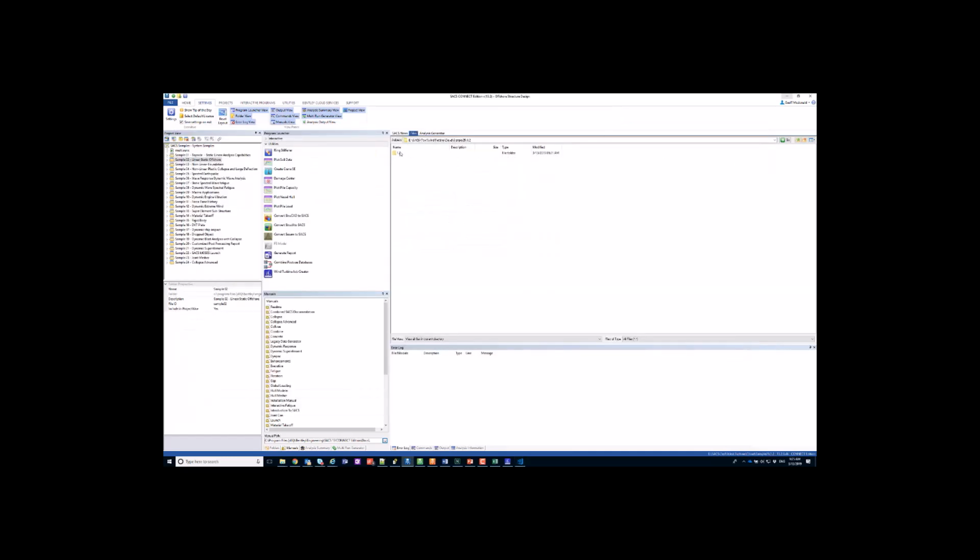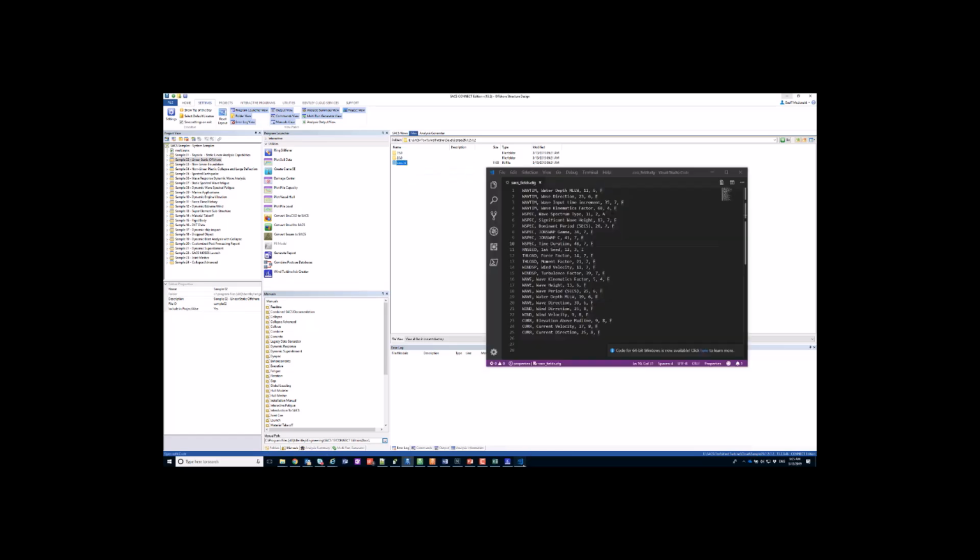It's also going to set up a SACS input file, which is going to be the input for the wind turbine analysis itself. I hope it's not going to take another minute just to load a text file, but it's looking like it may. If you're not familiar with the SACS input file, for this one it's pretty simple because it's for the dynamic superelement analysis, but it's just setting up all the different flags that are required and analysis input files, references, and in the cases of the strength and fatigue ones, it's going to be referencing some other data as well that are specific to those analyses. So it's going to automatically set those up.